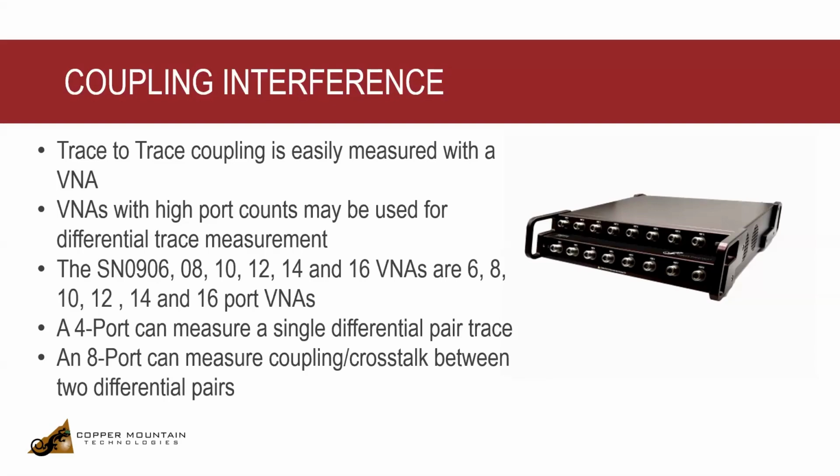So if you're doing high-speed FPGA design, you want to know what's going on the board. You want to know what's the isolation of the traces, what happens when it enters a connector and comes out the other side. You can measure all that, and you can use a time domain function to see exactly where it is. And you can kind of poke at it and determine whether it's capacitive or inductive, and what could you do to try to improve your design. So the time domain function is very, very powerful.